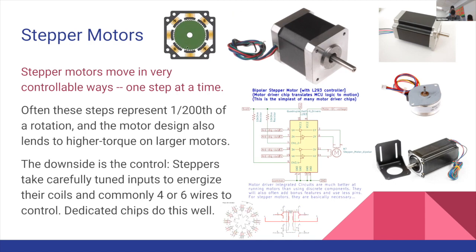Another nice benefit of a brushless motor is that there's no possibility for spark. Many of you have used a drill and seen it spark out of the back, or maybe even smelled the ozone that comes from the brushes. Brushes are a great way to get a motor to work easily, but they introduce a chance to reduce a little bit of torque. They have their own problems.